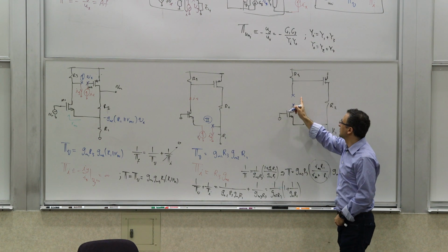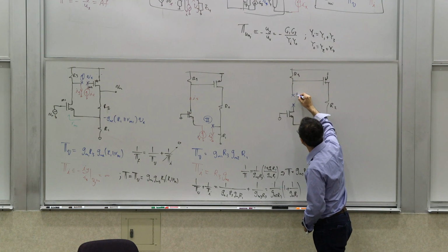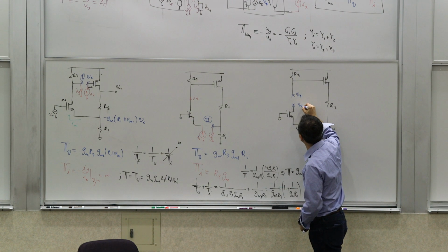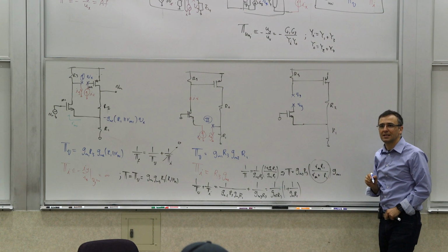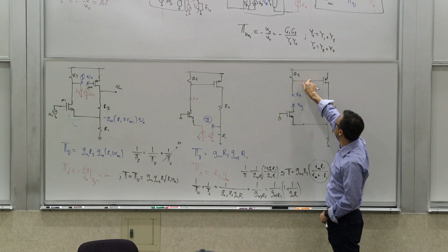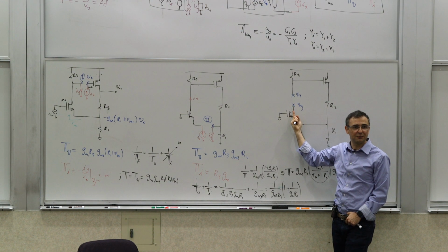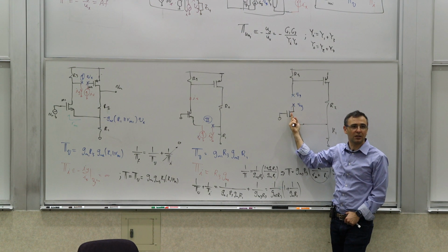So now what is the voltage loop gain here? If I apply voltage here, Vx, and measure Vy, what is that voltage? What is that return? Whatever it goes through, something goes through here, something comes through here, but then it's driving an infinite impedance. I'm ignoring RO, right?